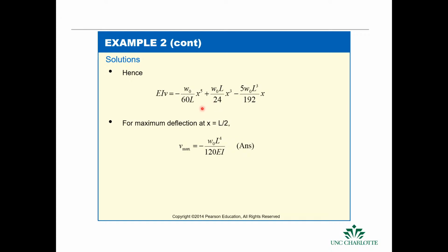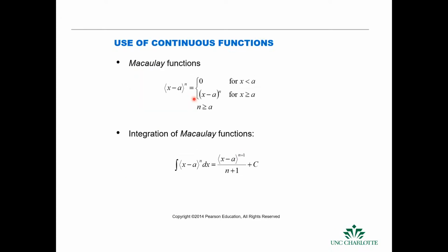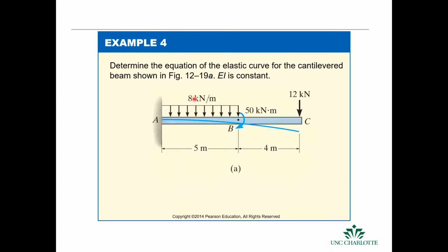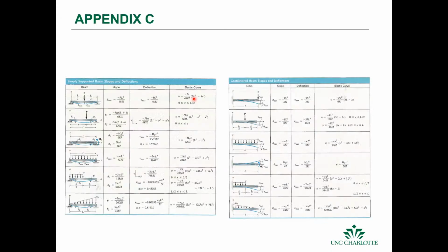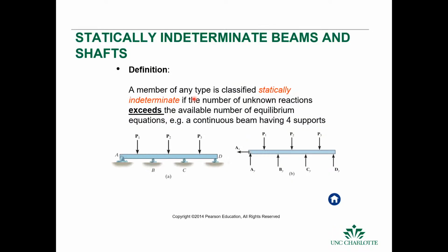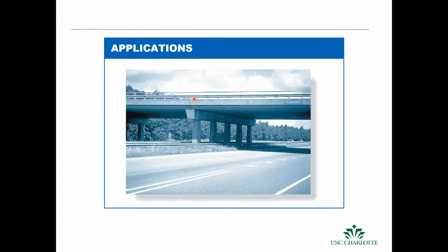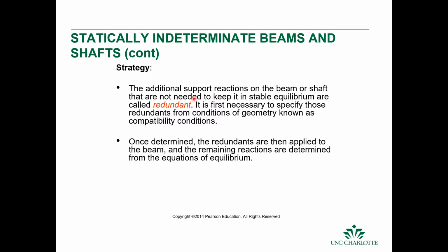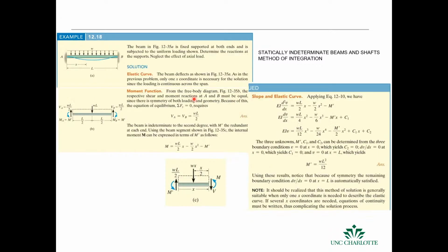I think I will mention one more thing though. We talk about beams. The cases that we covered, I would say, are undergraduate in the sense that we don't have enough time to get into all the details. But for beams, there's also statically indeterminate beams that we will commonly encounter in real machines. They're obviously all over the place, like bridges. And for statically indeterminate beams where you have an over-constrained system, then you can find which supports are redundant and then remove them and then find the reactions and then use equilibrium to reintroduce them.